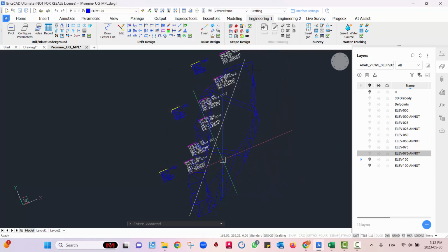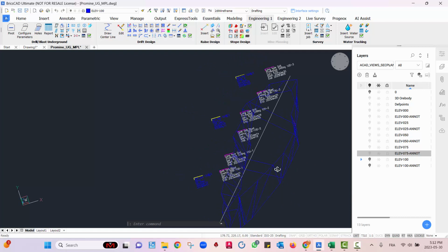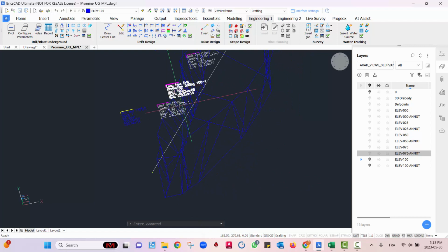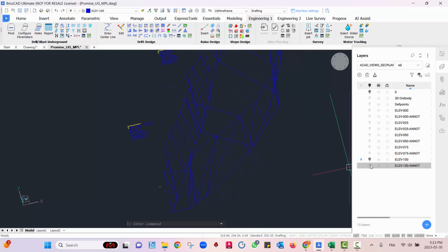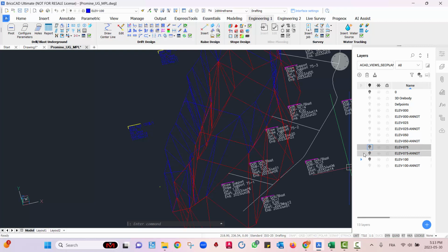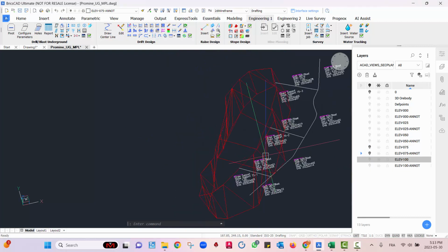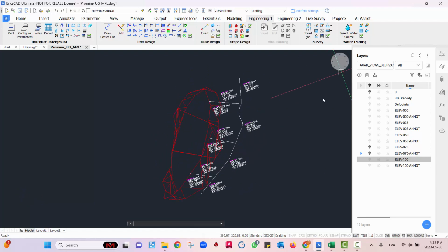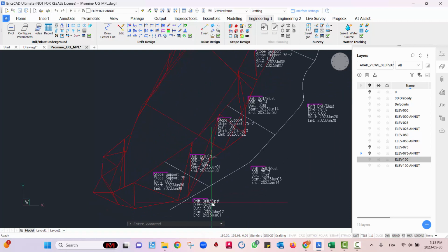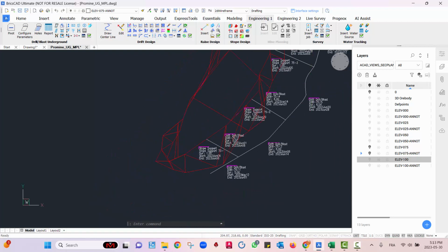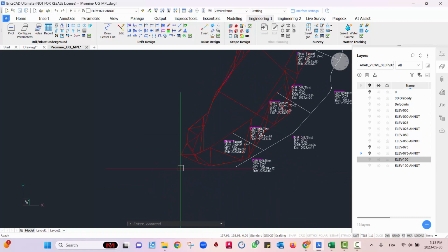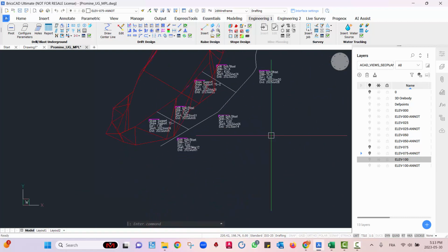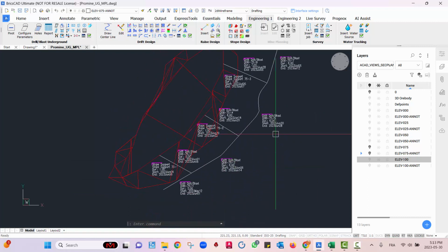Yes, okay. Now, what I'm going to do now is essentially design my overcut, but for level 75. So we're going to turn this off. Actually, turn these two here. Turn this one off. Okay. So what I'm going to do is first of all go to plan view, and here, as you can see, I already have my transport drifts configured. So what I'll do is design the overcut here along with the tasks and the mining blocks, and then we'll go down 1 level to design the same thing we have here.